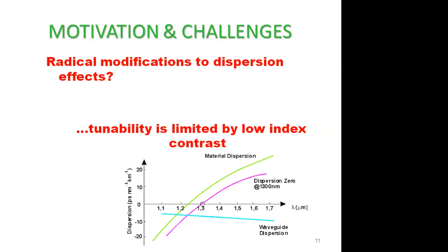What is the meaning of this? Zero dispersion at 1300. That means if you use at 1300 nanometer, there is no dispersion. Whatever problem we said, that will not be there, right? But what is the window we use for communication? Which window you use for communication? 1550. We use 1550. At 1300, there is a zero dispersion. You might be having doubt that use 1300. Why you want to use 1550?